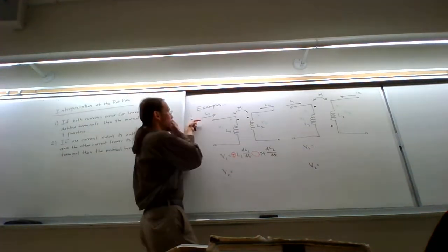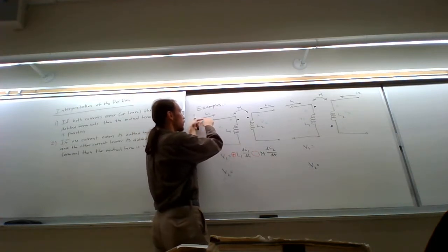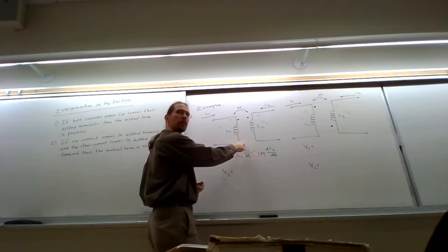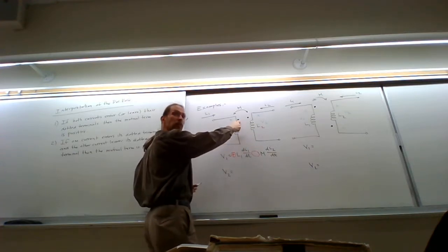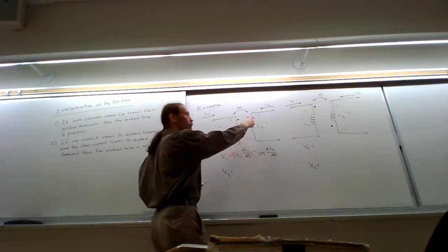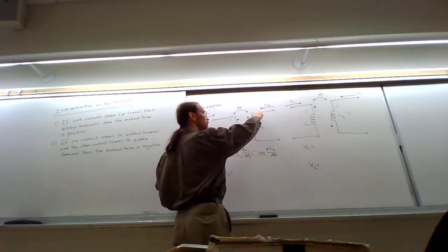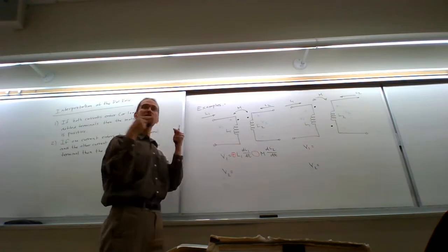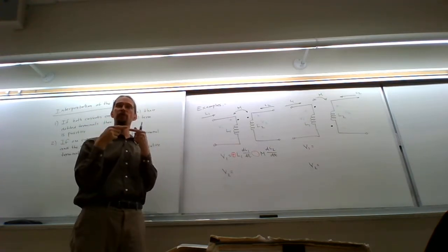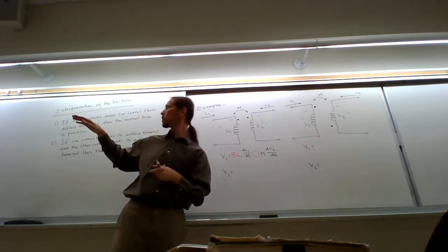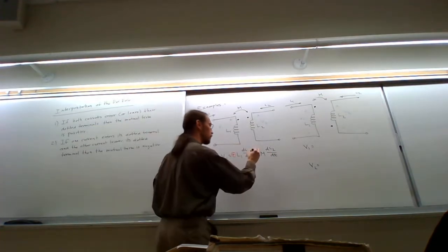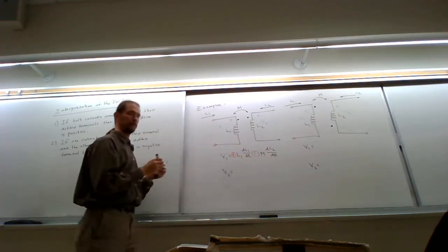So over here, if I take a look at I1, I1 goes in through here, it hits its dotted terminal, then it goes through the inductor. So this one is entering its dotted terminal. Over here, I have my current I2, it hits its dotted terminal, then it goes through the inductor. Both of those are entering their dotted terminals, which means, according to what I just said, this mutual term is positive.